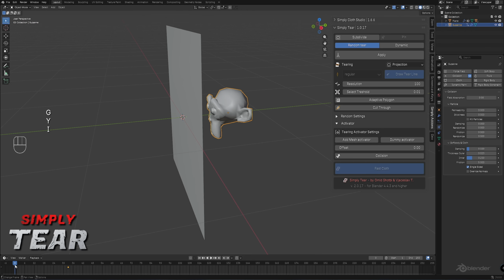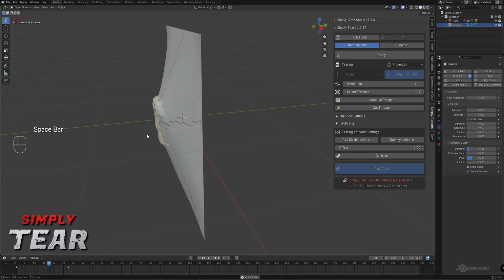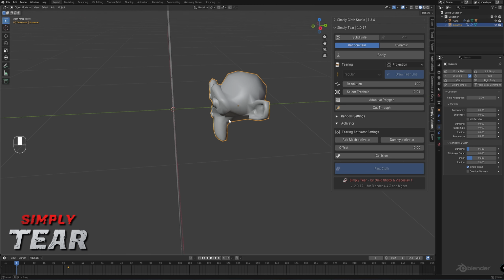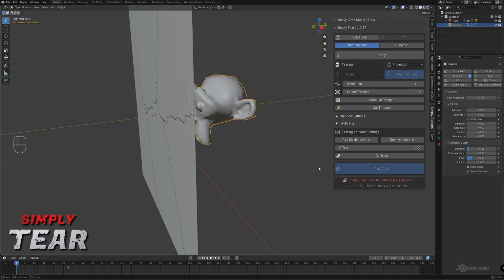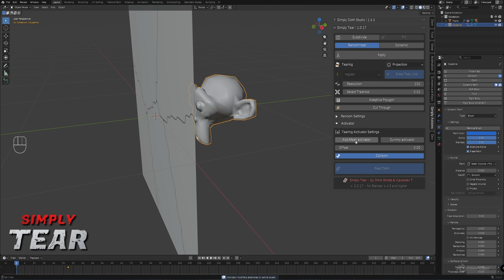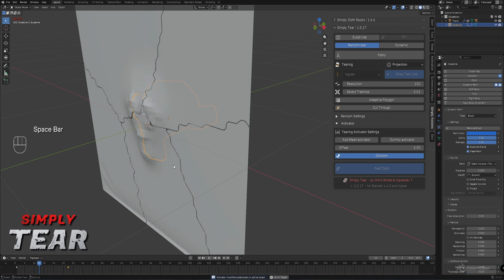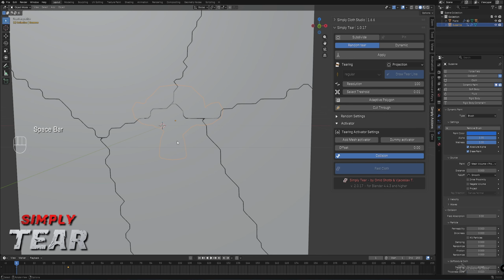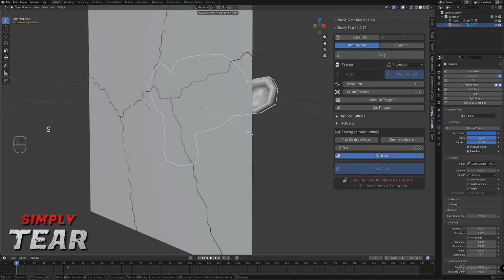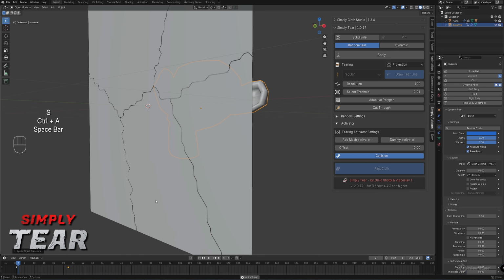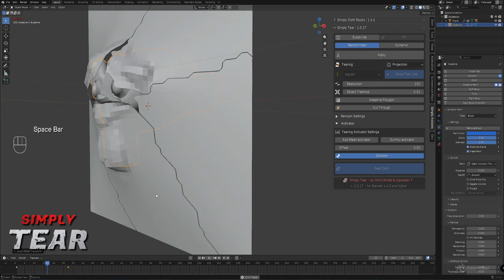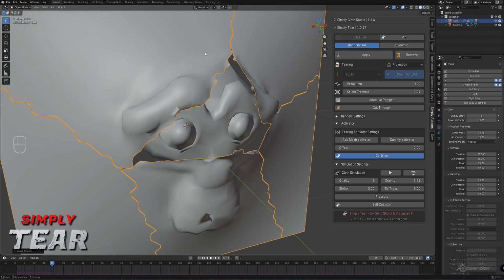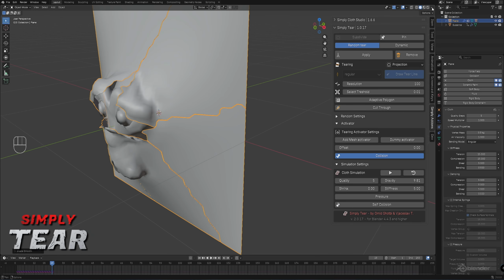You will see it's colliding, but it gets intersection, of course. If you want to have this as a collider and mesh activator, we can use this. Till it is touching the needed points, we can see there are no tearings here. We make it a bit bigger, and we will notice that if it's touching the cloth, it will tear.